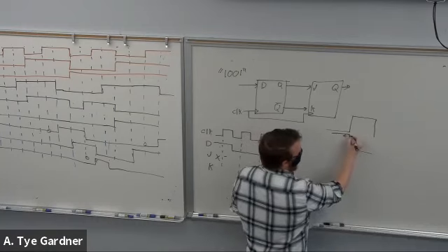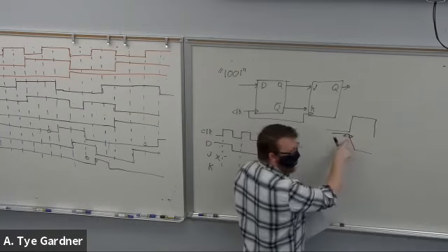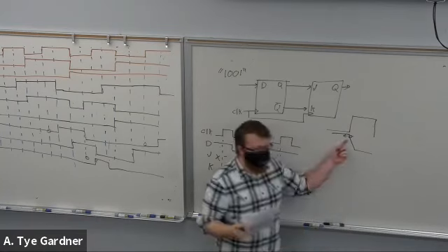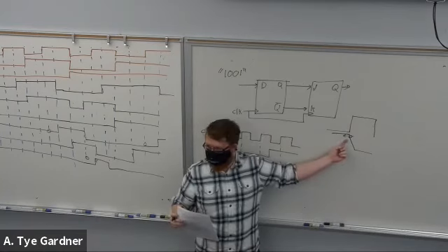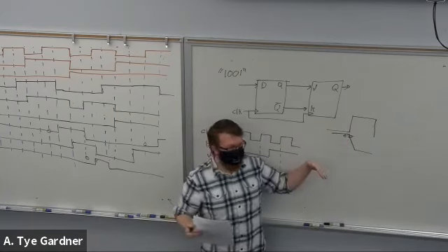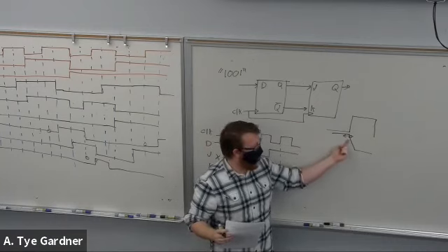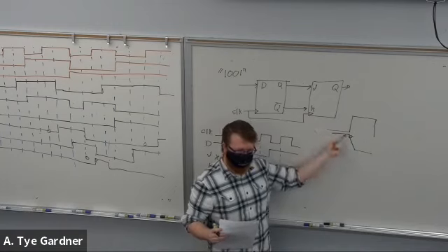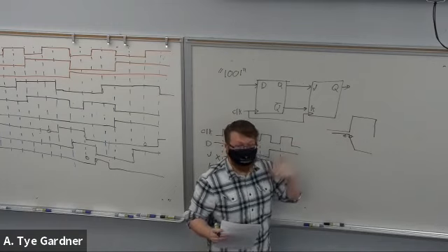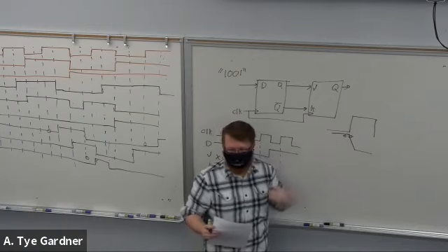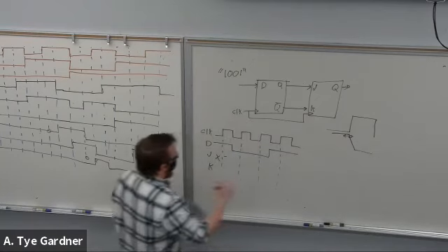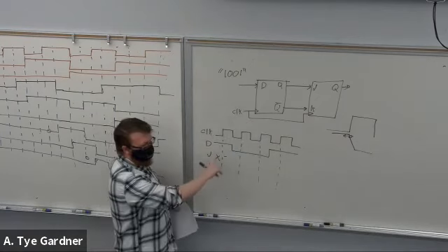So even if there's a little bit of delay and we take that point, just like in our lab 1, it has to decide, is that a 1 or a 0? Because it's not all the way up or all the way down. But because it takes a while to make that transition, it's always going to take the 1 or whatever it was before, right? Because it hasn't had an opportunity to change yet. So you can draw them as ideal devices